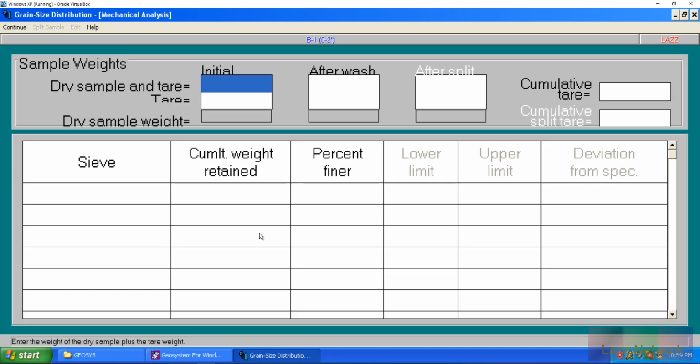So now this is where we're going to enter in our data from our actual sieve test. The sample size I'm going to be entering is roughly about 100 grams, and this data is from a proficiency sample that's technically a hydrometer, but with no hydrometer. So there are no particles that are finer, and we're not measuring the particles finer than the number 200 sieve, which is all a hydrometer tells you.